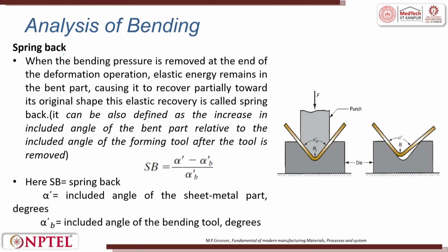Now, let us try to understand the important concept in sheet metal called spring back. Why does spring back come into effect? Because when you look at the stress strain curve, it has an elastic region and then it gets into a plastic region. When we try to deform plastically, if you are not properly into the plastic region, there is always a small amount of recovery that happens, which leads to the spring back.